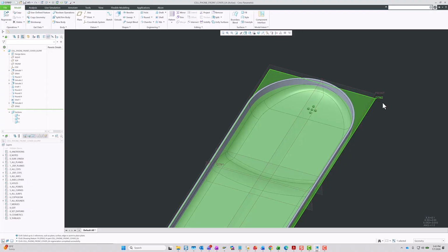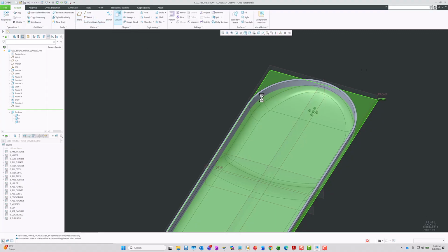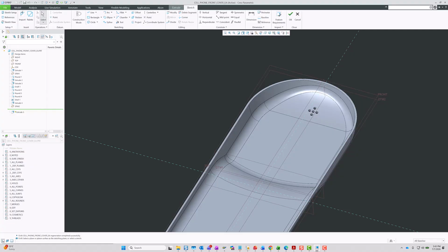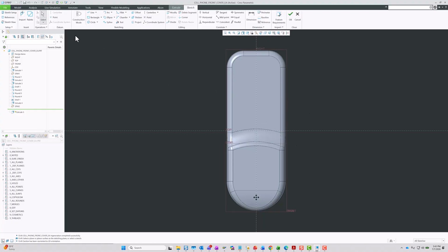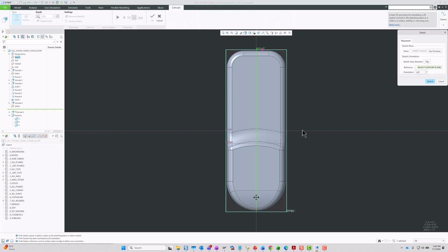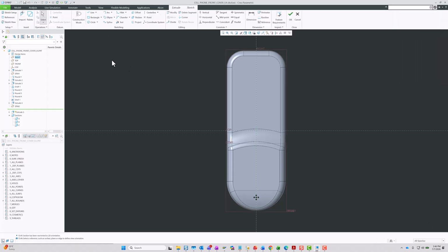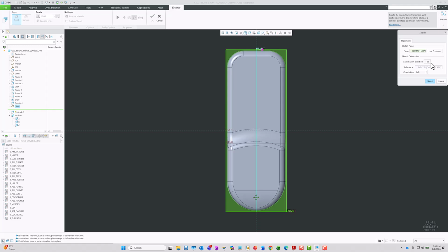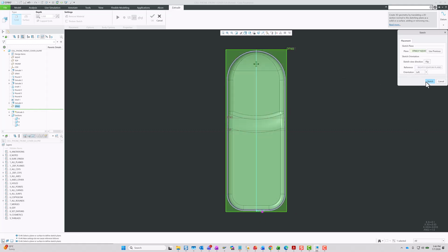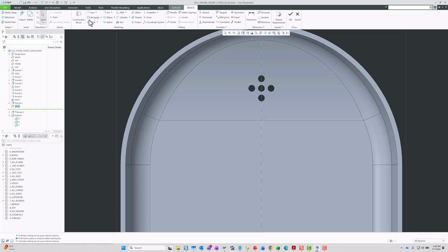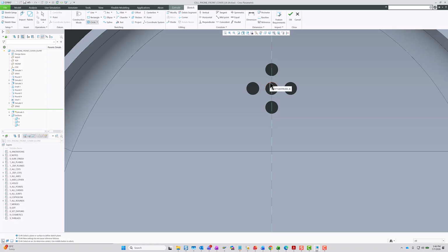And from this new plane, we are going to extrude a new circle. So let's click sketch view. And let's set it up correctly. So let me show you again what I did. I will click in the sketch setup, flip, and I have the correct position. Sketch. So what I'm going to do is to select the concentric tool. I will select the hole in the middle, and then I will extend a circle here, and I will change the diameter to 0.28, like this.